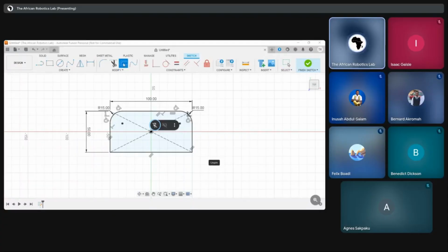So we have selected the offset tool. Now it's saying select curves. Okay, so let's select it. Now we have selected it. After selecting it, an arrow appears here. We can click on the arrow and move it outward or inward to create a twin of the outline that we have already created. If you want the curve to be in, all you have to do is give it a negative value of, let's say, negative 5 millimeters. So negative 5 millimeters, and then let's click enter. Great.